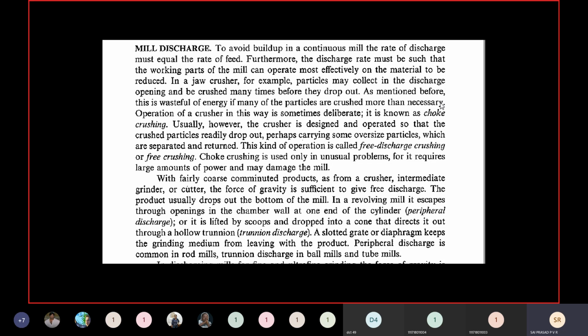So that is important. In the initial stage, if the particle is breaking, then what will happen to the fine particles without touching them? They try to come out. Here we'll see one more point: the orientation of the particles through the crushing zone is also very important. How are we charging them? You charge them such that the narrowest opening is passing through the clear opening. That is important. This point we study elaborately in our fourth week. Don't worry about it.